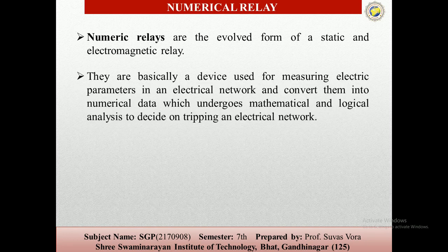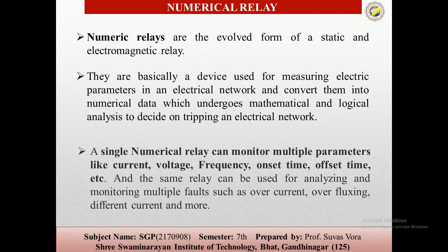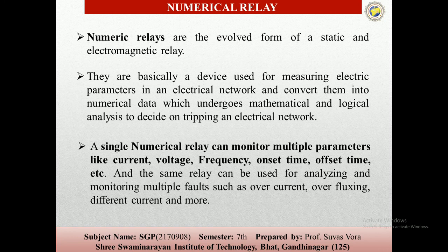So the signal from the CTs and PTs is given to the low pass filter, and it removes the unwanted frequency components. So this is given to the analog signal conditioning. The signal from the signal conditioning circuits is sampled using the sample and hold circuit. The signal from the signal conditioning circuit is given to the analog multiplexer, which accepts more than one input and gives one output.